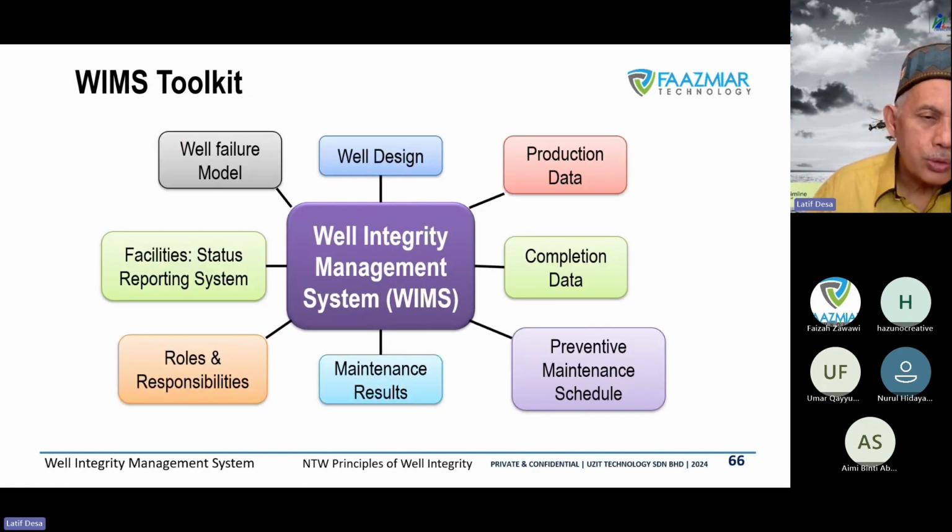Okay, so the toolkits for the well information management system. Sometimes they put the well design package inside there to see whether you put the casing there with the pressure rating. We have the burst pressure and casing pressure for the tubing, for the casing, and the well design tells you whether it's going to be cemented to surface or cemented to a certain level. It's all there.